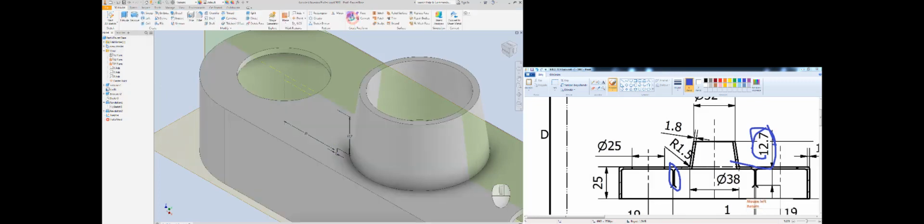I will just turn this. Have the 12.7 millimeter in height. Finish my sketch first. To show you what I'm doing, I will just turn my point of view from the box on the other side. I have the sketch. I will just make the extrusions by selecting the two command.